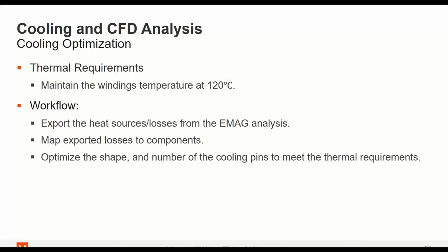And of course, we progress to the final section of the presentation, where we discuss the cooling. And as we mentioned from the detailed demagnetization analysis, for that given motor, we have to maintain the temperature in the windings at 120 degrees Celsius or even below.